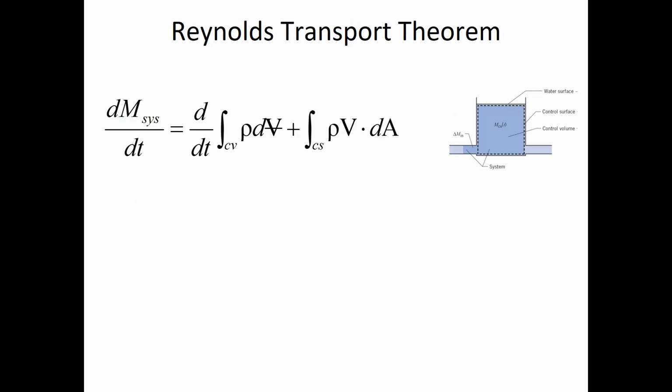In class last time, we did a couple of examples where we ended up saying that inside of some control volume, the accumulation is the difference between the in minus the out. We were looking at flow in and out of a control volume, abbreviated CV. Remember that the outside surfaces that encompass that control volume are the control surfaces, the surfaces through which the system flows. And we defined the system as a continuously connected mass of particles. It's the same stuff.